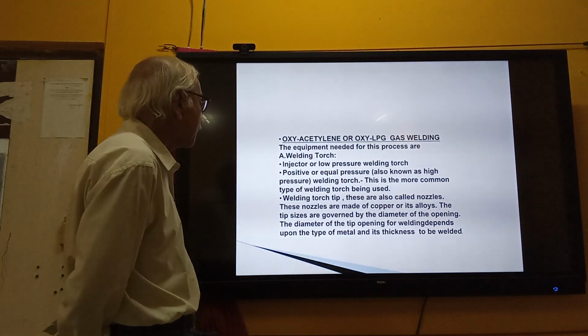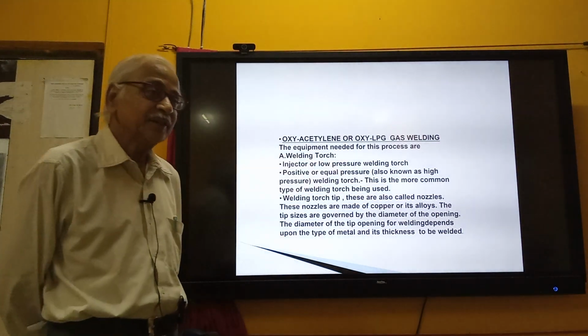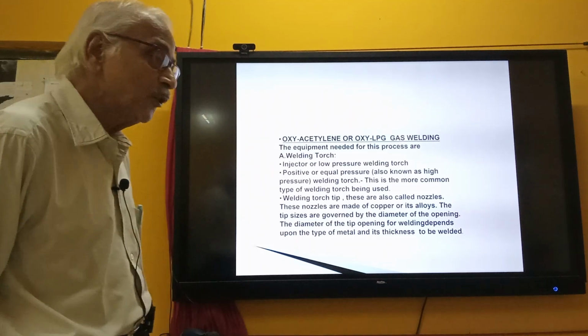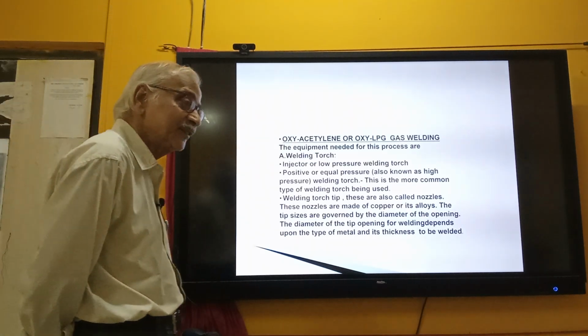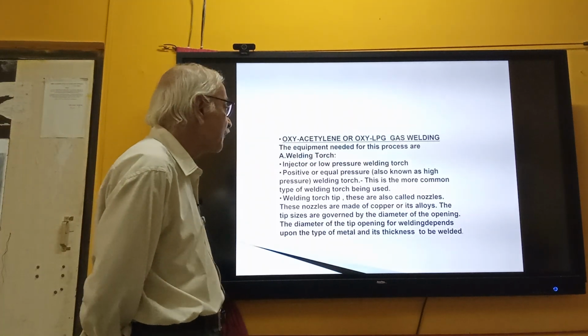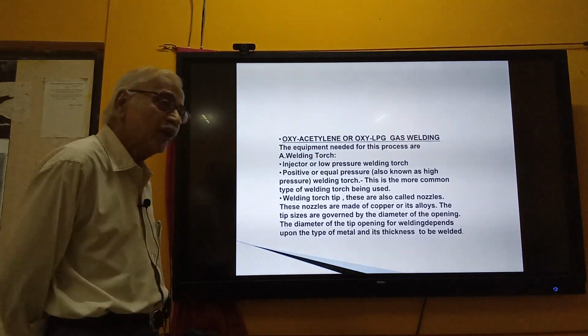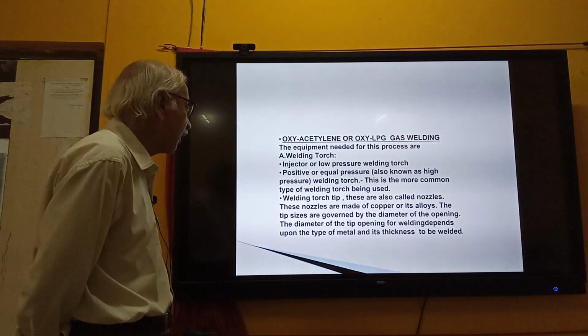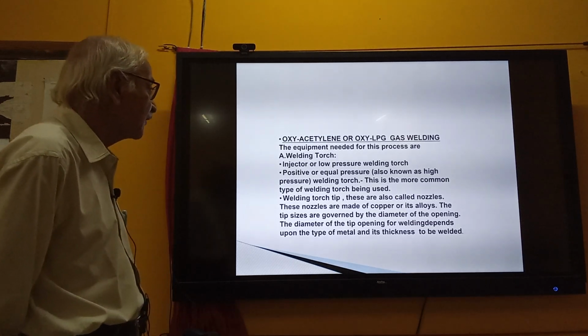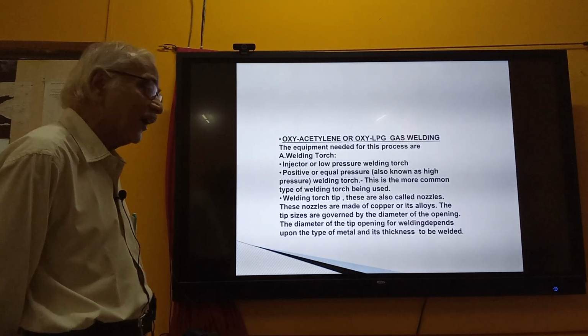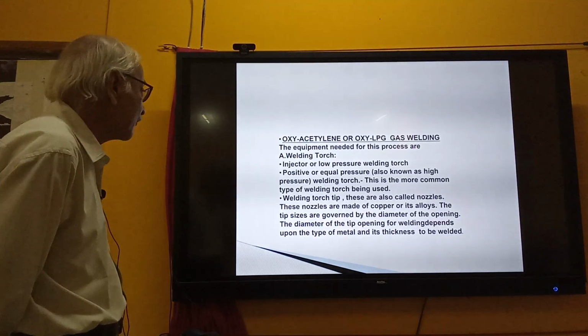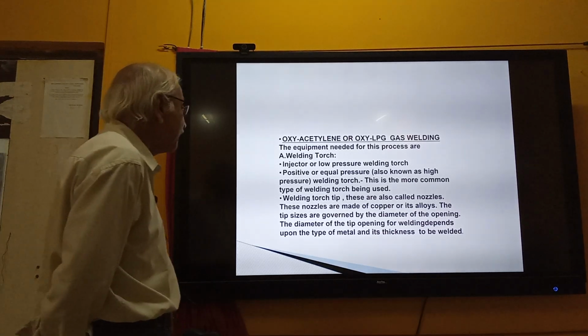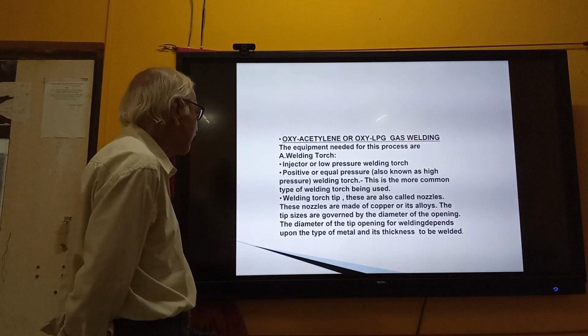Now in case of welding or cutting, much more flame energy is needed than cooking in the kitchen. So we have to add extra oxygen in this process, and that is why this process is known as oxyacetylene or oxy-LPG gas welding. The equipment needed for these purposes are a welding torch,